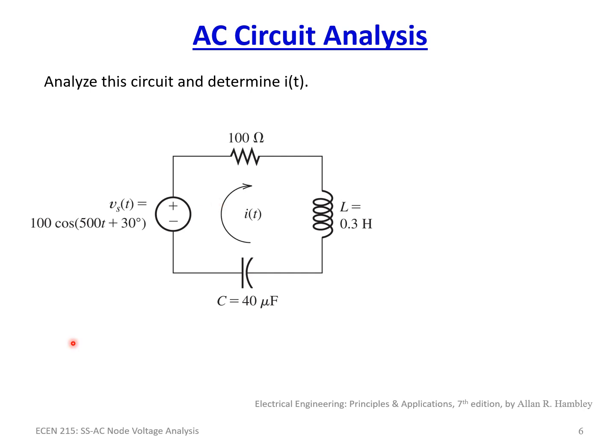So if these were resistors, we would know exactly what we would do. There's various methods. We could do mesh current analysis, which we'll talk about doing in AC analysis in the next lecture. But this is actually fairly straightforward. If this was three resistors in series, what we would do is add everything up, get the total resistance of the circuit, the R equivalent, and just take Vs divided by R, and it gives us I of t. So we just simply use Ohm's law for this.